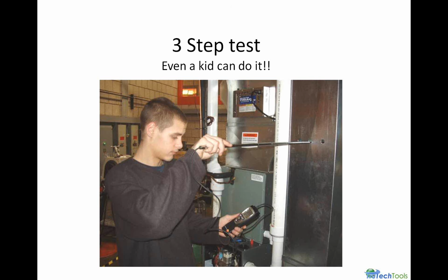You might tell me, oh, the customer doesn't want me to drill a hole in the ductwork. Well, you go to any commercial job, you go anywhere to measure airflow, you have to make a hole in the ductwork to measure airflow. There's no way around it. You've got to somehow do that. Even if you're going to measure temperature, you're going to make a hole in the duct. The key is just putting a nice plug in there so it looks good when we're finished.